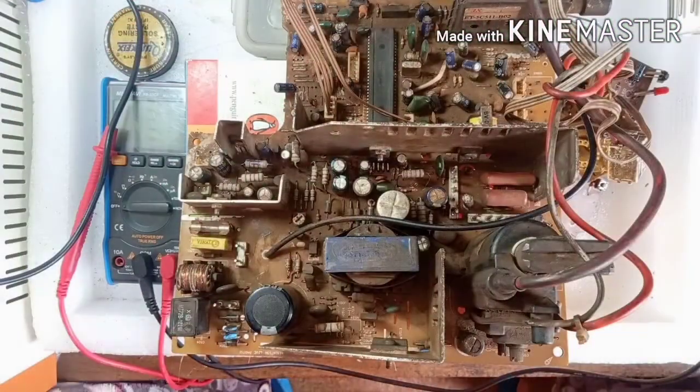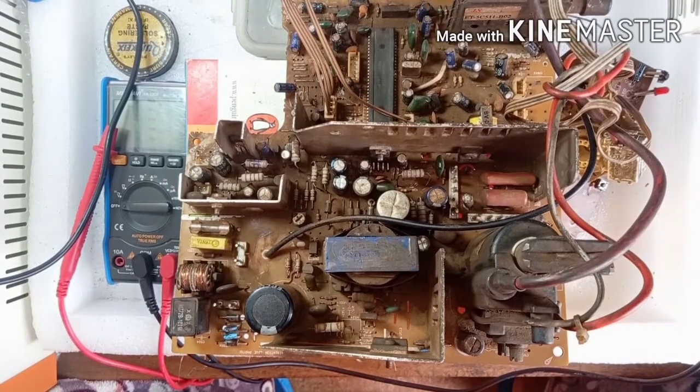Okay, since the power supply to the vertical section is normal and indeed the vertical IC is receiving enough power, yet we still have vertical faults, this could be due to a defective vertical IC, so this might be the time I replace it. But before I replace the vertical IC, I will check the voltage regulator within the vertical circuits.